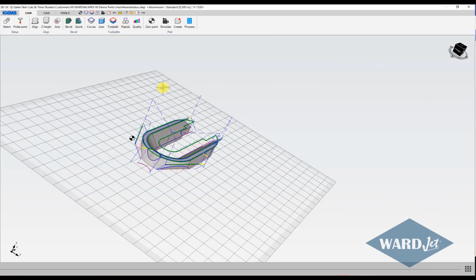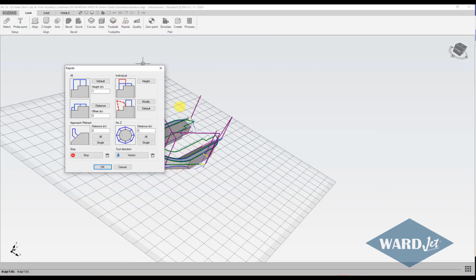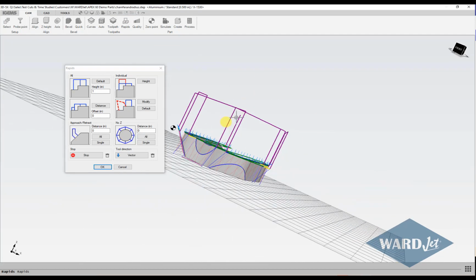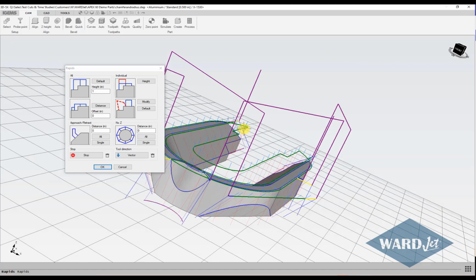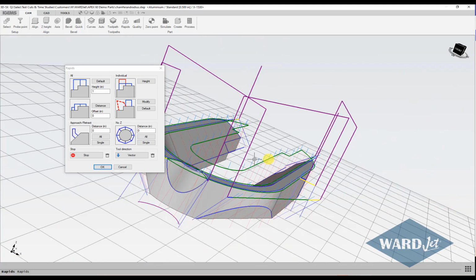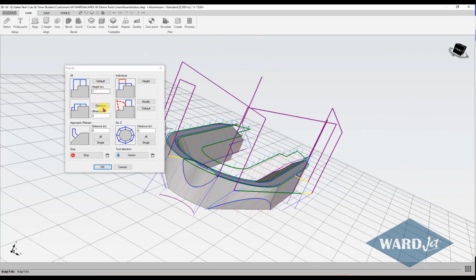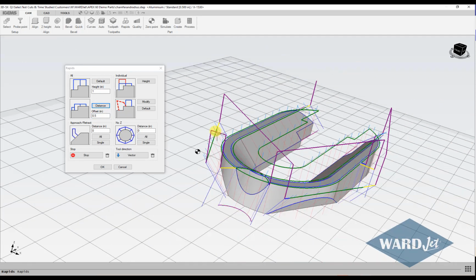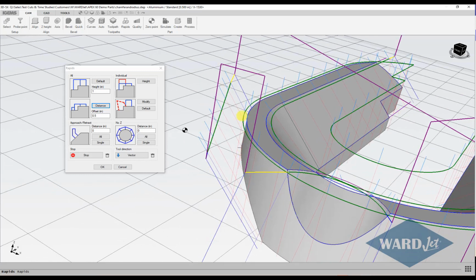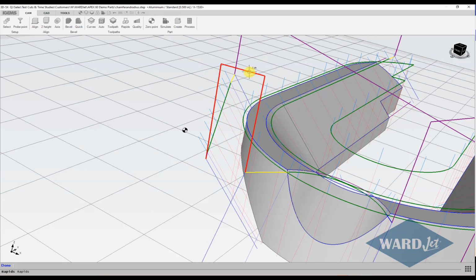once you've got your toolpath the way you like it, you can click on this Rapids button here. So we're not going to have a whole lot of things to worry about for tipping up this little guy here maybe, but a couple times I've done this, he lays pretty flat. But if we did want to lift up less, you can come in here, click on distance. On a particular cut, say going from this cut to this cut, there's not going to be much of an issue.